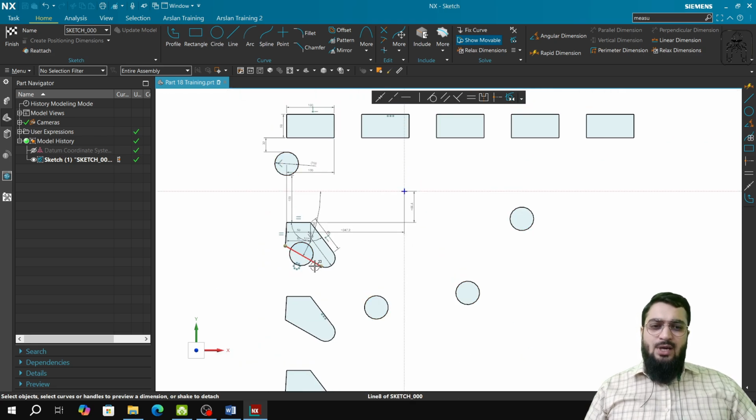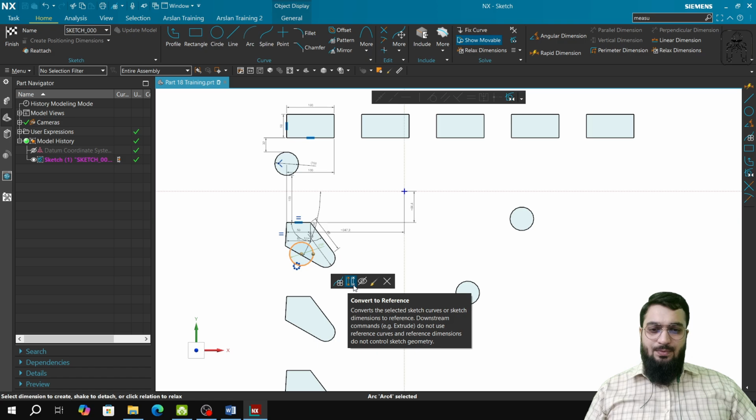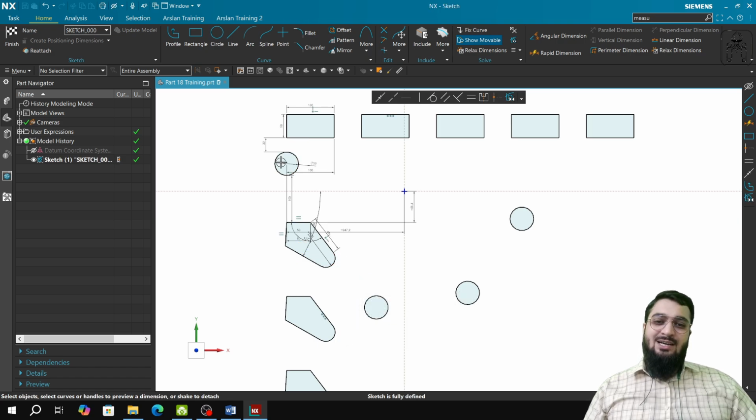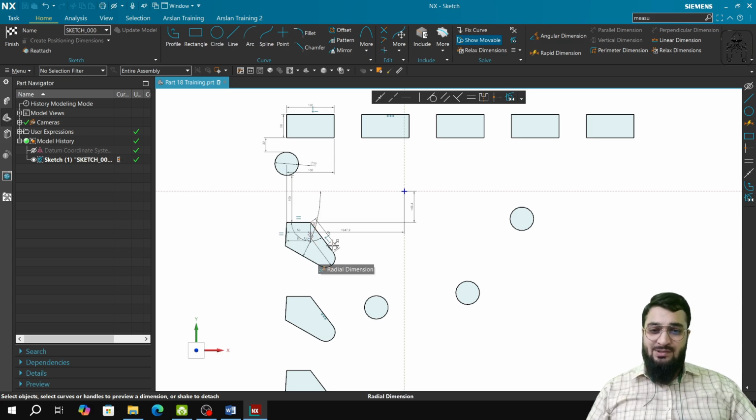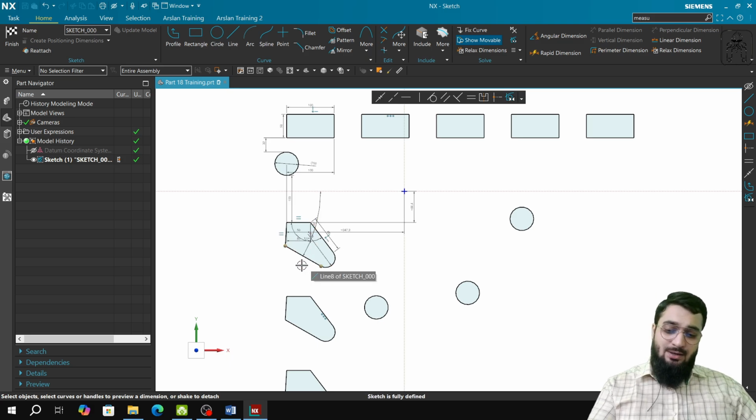So now if I want to suppress this feature, you will see the option of hiding it. The pattern has been created with the pitch and span we wanted, but this one I do not want as it is interfering with this sketch. I just hide it.